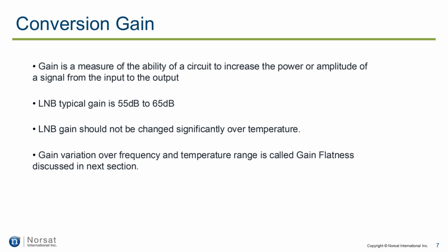The typical gain of an LNB ranges between 55 and 65 decibel. It is a critical parameter to achieve better receiving quality. The LNB gain does not perform evenly along the multiple frequencies that the LNB operates.